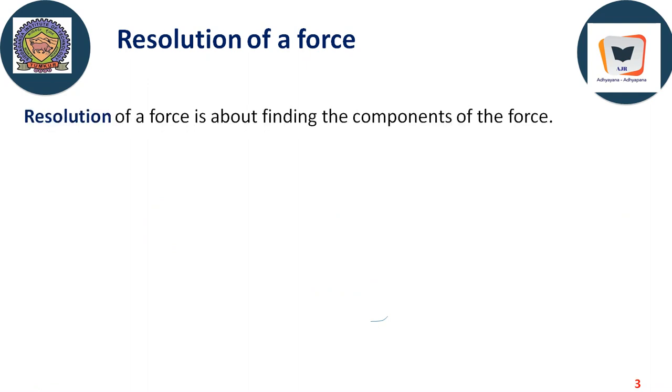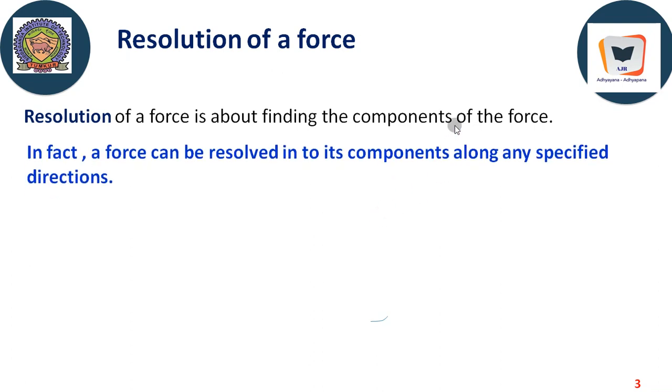And this procedure of breaking an inclined force into its components is called the resolution of a force. Resolution of a force is about finding the components of the force, one in horizontal direction and one in vertical direction. It is not that we always resolve the force only in two directions, horizontal and vertical. In fact, a force can be resolved into its components along any specified direction.